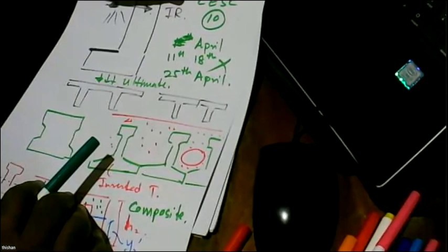Can we achieve a complete crack recovery as mentioned? I mean, 100% crack recovery? Yes, provided concrete does not crush, right? And if you want a real recovery, then the ideal is going for unbonded tendons. Because when the tendons are bonded, if the loads are extremely high and the steel yields, then you can't have 100% recovery, right?